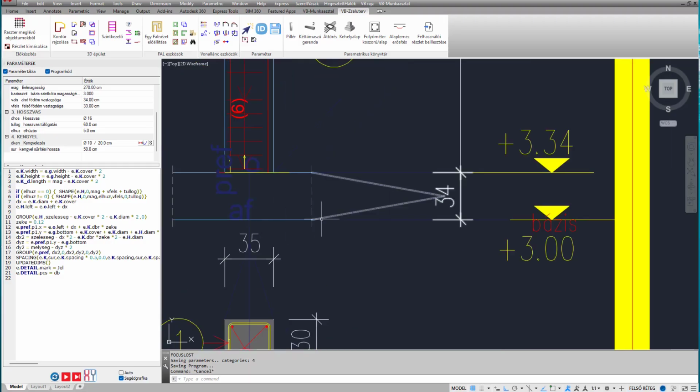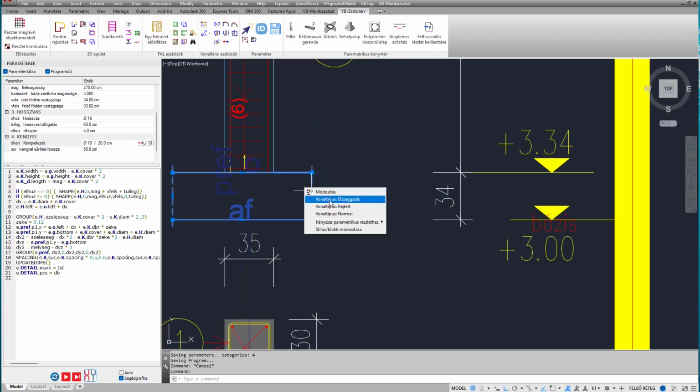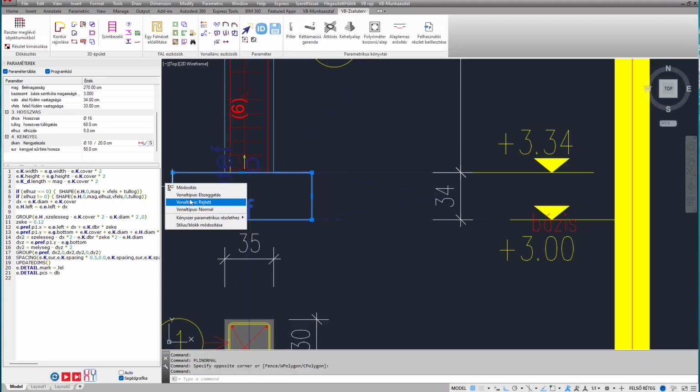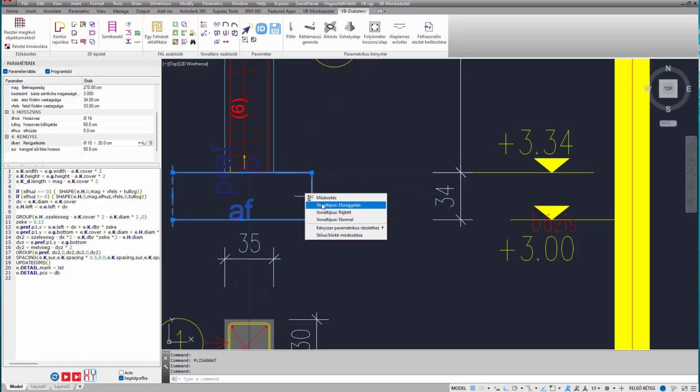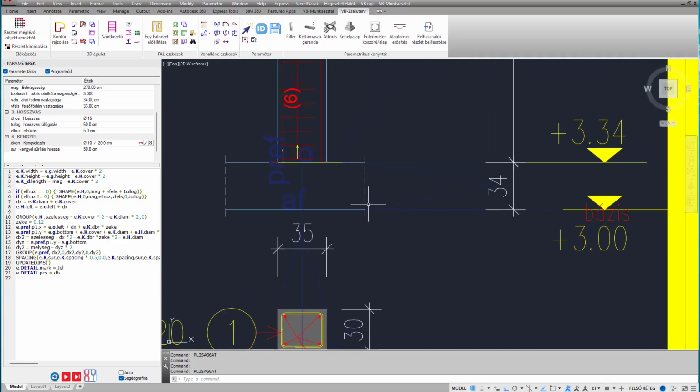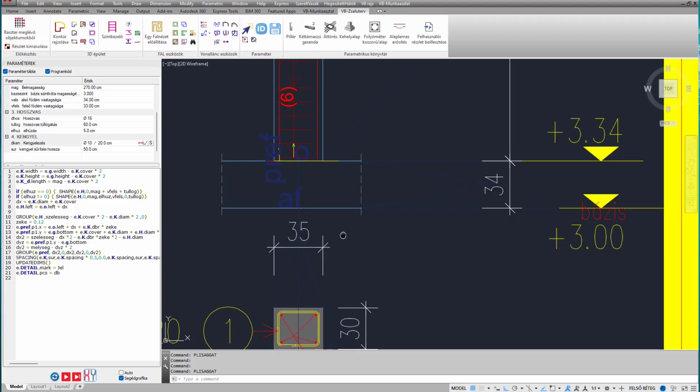Although it appears to consist of 4 separate lines, in reality it is just a contour object with a dashed line type set at the 2 edges. If I switch it to a normal line type, it becomes immediately clear that it is a square. A contour object has a contour style where color, fill, and various other parameters can be set. It is also important to know that contour objects can be named using object identifiers.